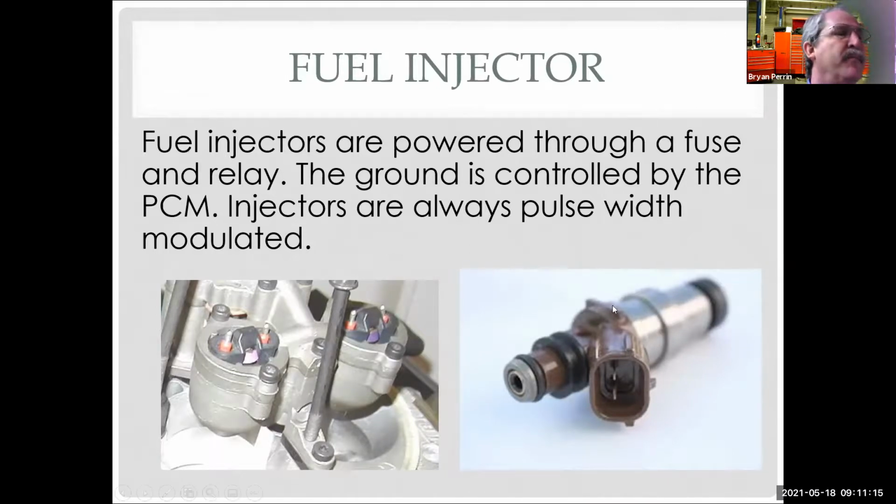And the computer, on injectors, I can't think of any on gasoline engines where the computer does not control the ground side of the injector. So power is supplied by a common power source. Power goes to all the injectors, and then the computer controls the ground to each injector separately.